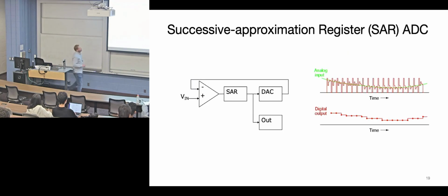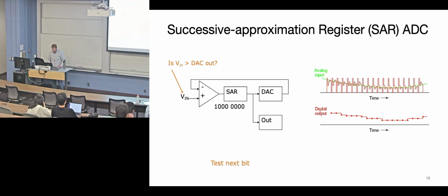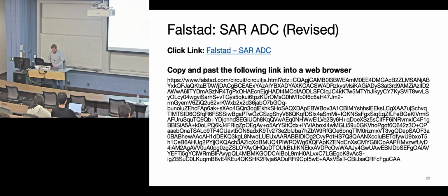This is just another example of showing how you could do a binary search as a function of time if you had a time varying signal. Basically, you sample, you do a conversion to some value, then you sample again, conversion. And so the output here is going to be some binary value that's just represented there. All right, so let's see how it works. Showing that you're going to step through the search algorithm to find the value. Okay.